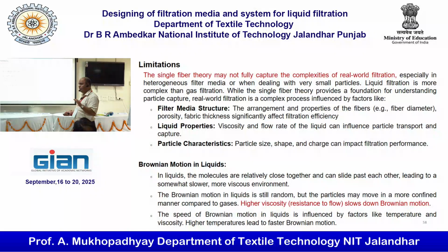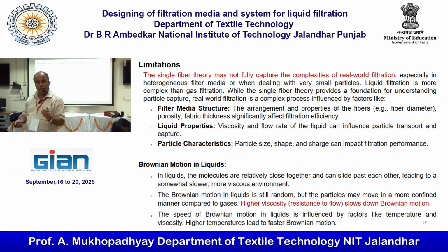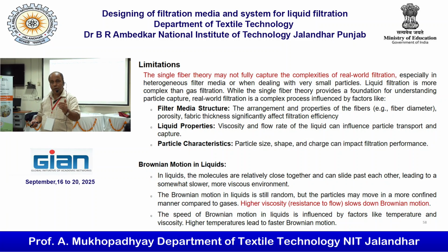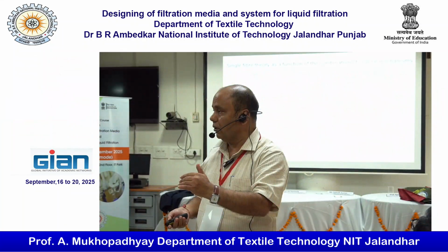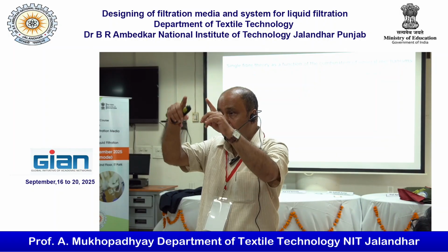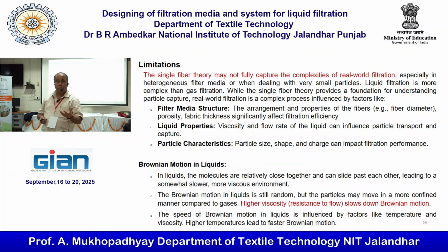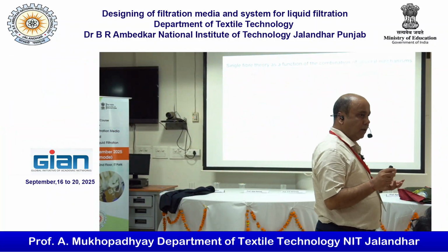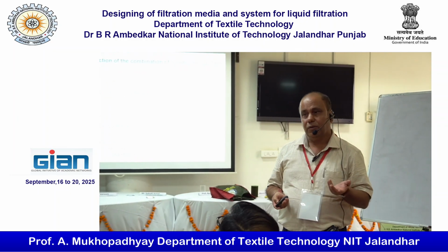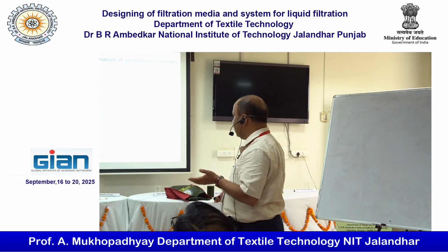And Brownian motion in liquid will obviously be very slow. Again, whenever we talk about single fiber theory, it has a lot of impact from the size of the particle, the velocity of the particle, and the temperature of the stream. If you change the velocity, particles which are showing Brownian behavior may start showing interception. So that can happen. It is not an ideal situation that 0.3 will always be our worst case, but usually in a common case we get 0.3. Again, in a static environment it will change. So there could be a lot of other parameters which can change this value.